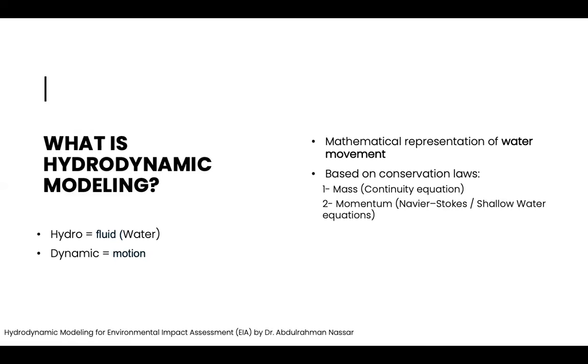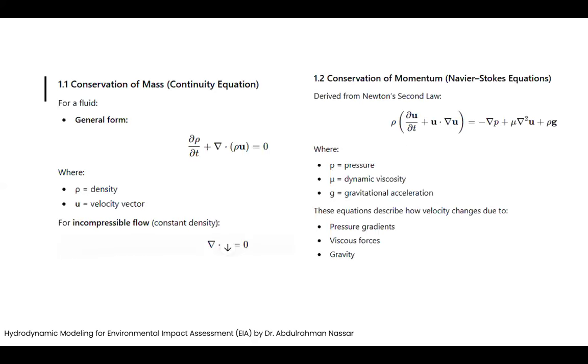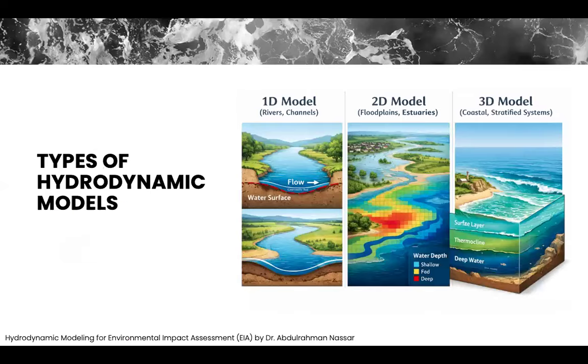It depends on two laws. The first one is about mass, which includes density as a variable and the velocity vector. The other one is about momentum, which is about pressure, dynamic viscosity, gravity, acceleration. And there is another equation about energy. So all of this is the fundamental equations for all models that we use in hydrodynamic modeling.